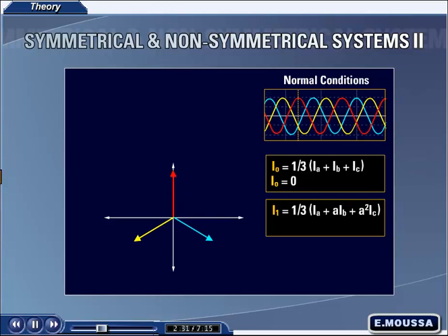Positive sequence uses the formula IA + aIB + a² IC. We notice that phase B has an a operator applied, which will rotate the vector 120 degrees counterclockwise, lining it up with phase A. Since the equation calls for these to be added, we will place the adjusted phase B above phase A. Phase C has an a² operator acting on it, which rotates the phasor 240 degrees, also aligning it with phase A.